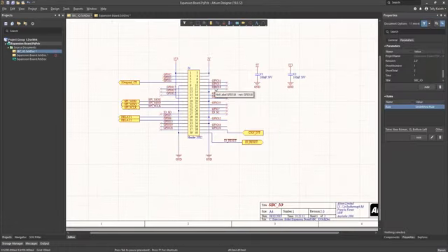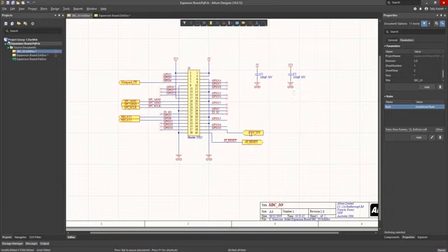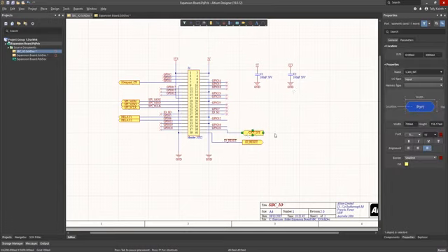Looking at the SBC I/O schematic, we see several ports and net labels. Selecting a net label, we can see its properties in the Properties panel. If desired, we could edit it here. Likewise, selecting a port, we can edit or update its properties. In this case, CAN_INT is set to the type of I/O input type.